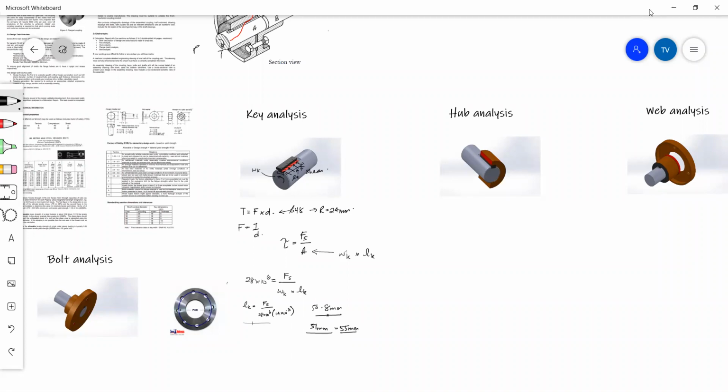So this value here is not T. Okay, this is not T. This is tau. This is a tau on its own. For shear, it's called tau, and for tensile and compressive, it's called sigma. So it's not T, it's actually tau. So we can't actually substitute T in place of this shear stress value.